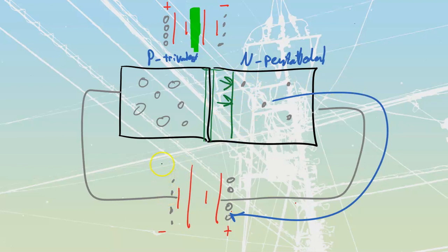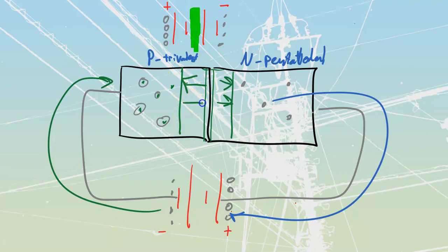It's going to start to move outward as we suck all those electrons out of that side over there. On this side of the battery, we are going to deliver a bunch of electrons in, and as we deliver those electrons in, they're going to fill each of these holes over here. It's going to do the same thing. We're basically going to be moving our depletion region, making it larger, and this depletion region acts like an insulation.